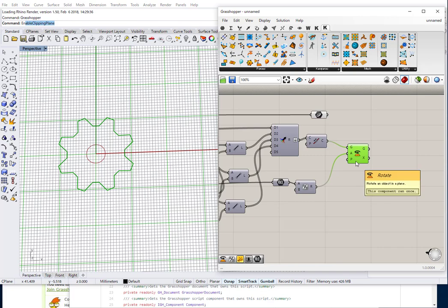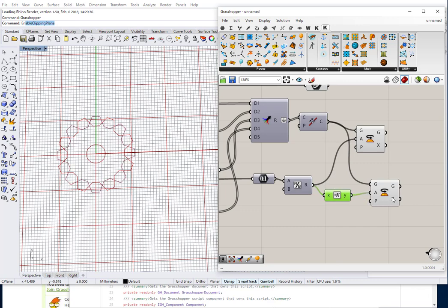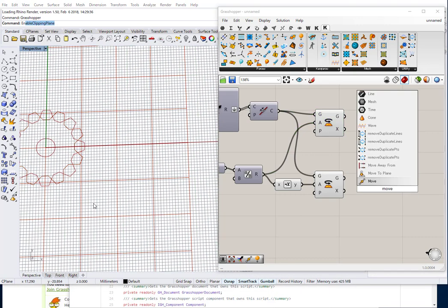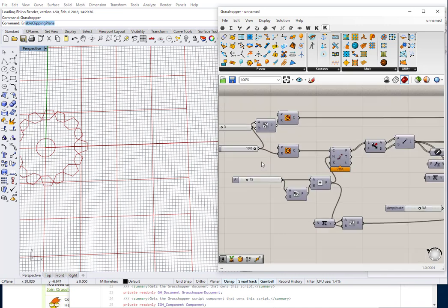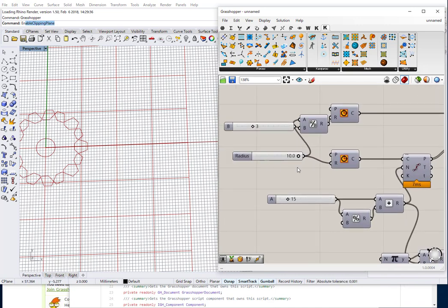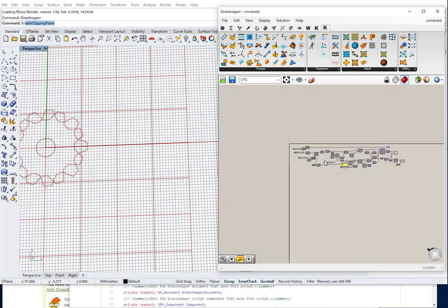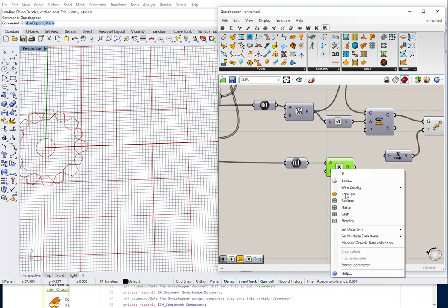And the other one, I can use the negative value here. Okay, and I can move this to the right, to the x direction for initial position. So how much should I move? First of all, the diameter of the circle, so I should bring this parameter here and multiply it by 2, because this is the radius.